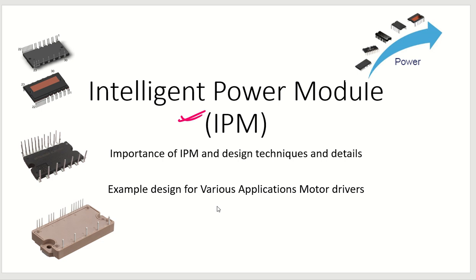First of all, you can see we have IPMs which integrate a lot of other parts, whether it is an IGBT or gate driver, or sometimes shutdown facilities, or a temperature sensor device, or so many other things, as well as our three-phase motor driver. So basically, why do we go ahead with IPM?